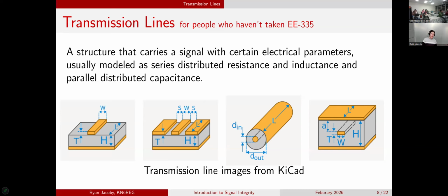Oh, yes, they also provide a very clear return path for your ground current. If you just route a wire out and then connect something to it, eventually that current is going to have to come back to whatever source is supplying it. If you feed it with a transmission line, that is very controlled: my current is going out the center and coming back on the shield. And yeah, given enough size, everything becomes a transmission line.